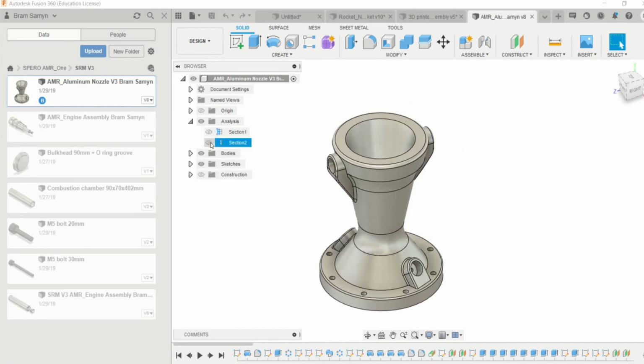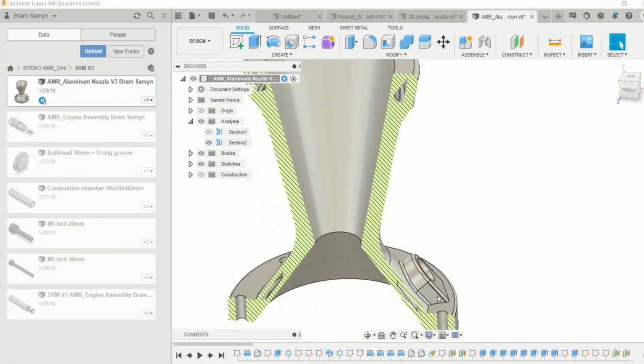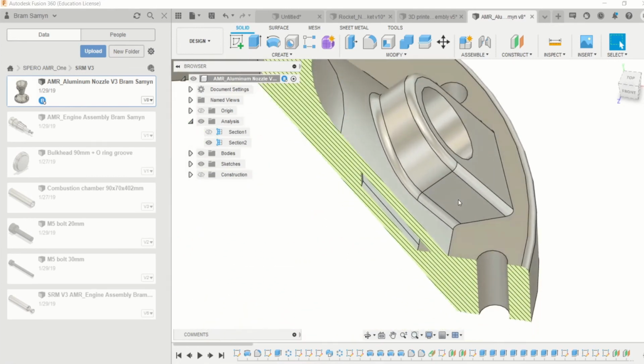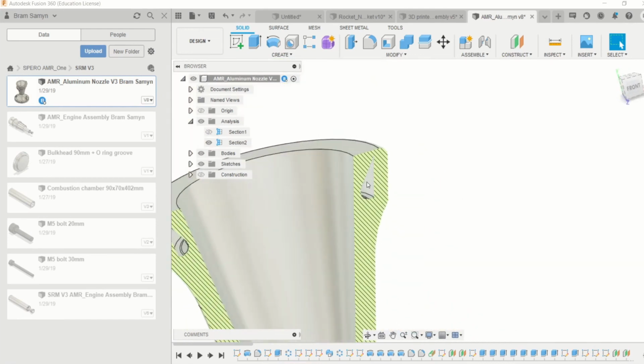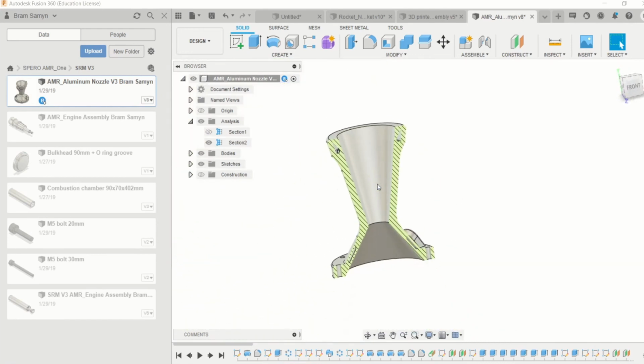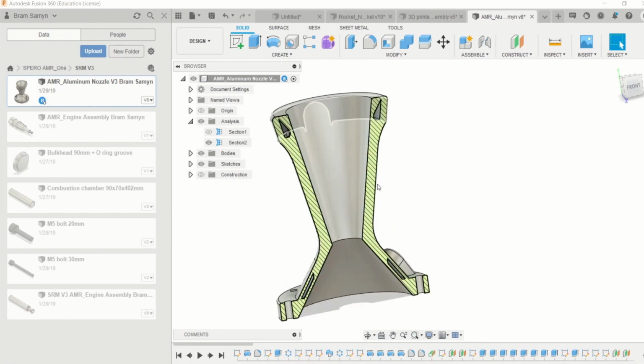That is because for 3D printing you need to stay below a certain angle. Otherwise, if you have an overhang that is much higher than 45 degrees, the printer could have some problems creating those cavities in your model. So that's why I tried to use this rule of not having an overhang greater than 45 degrees, so that there was less chance of the part failing.